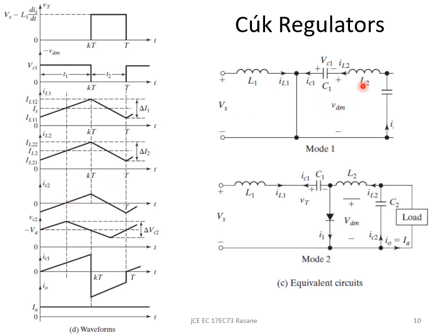That is because of the capacitor and inductor coming in series. So we will have the average, because this capacitor is only going to carry the ripple. It will not carry the average current. So whatever this ripple is, it is going to flow through this IC2. Okay. Next, and its average value will be 0 current value.